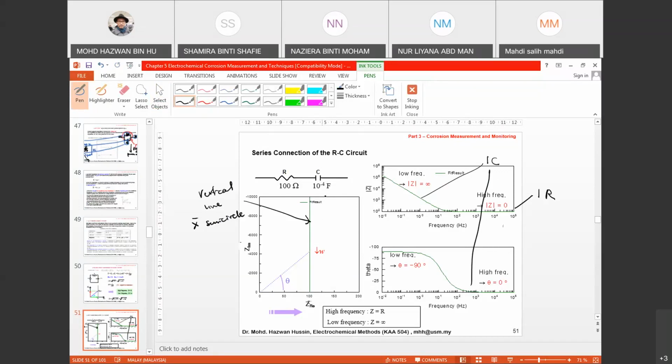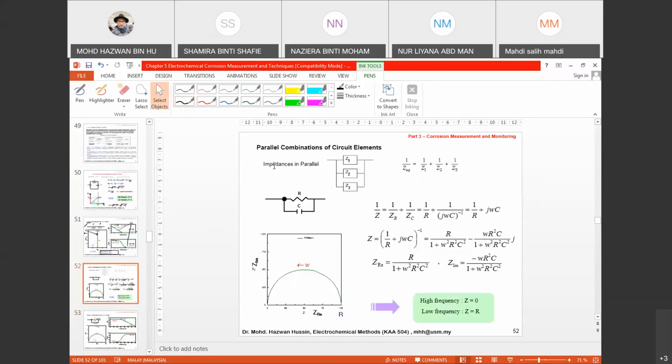Okay, so with this kind of thing, I already know: one resistor, one capacitor, and it is a vertical line, so I have a series design, side by side, not a parallel design. Okay. So what would this one be? You see the Nyquist plot actually forming a semicircle.